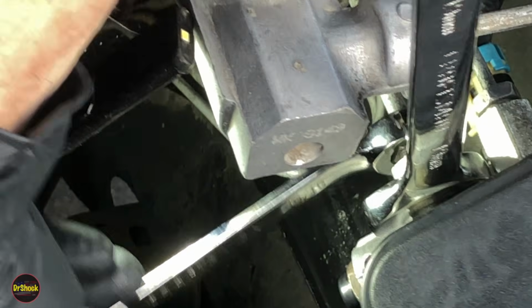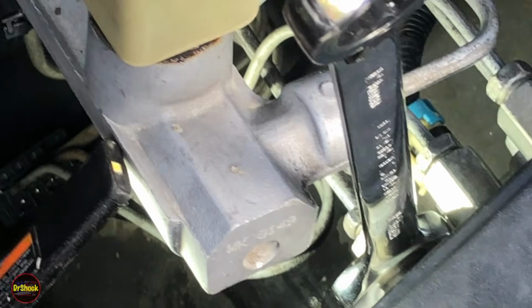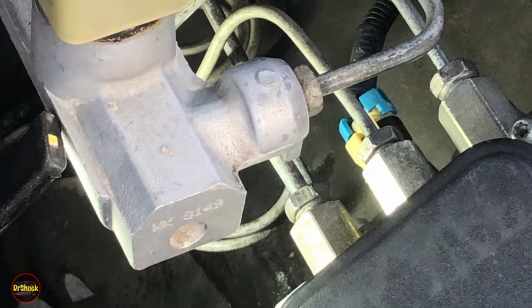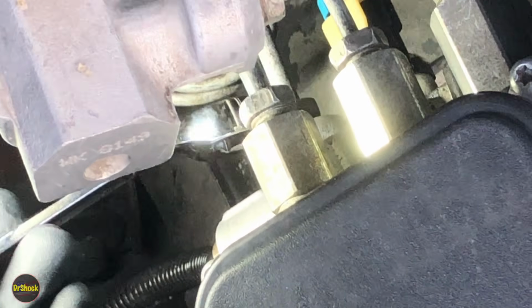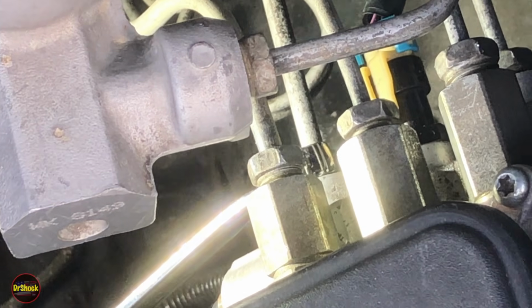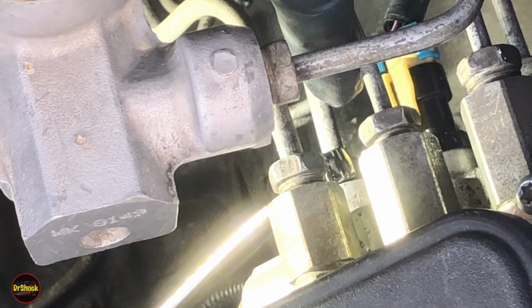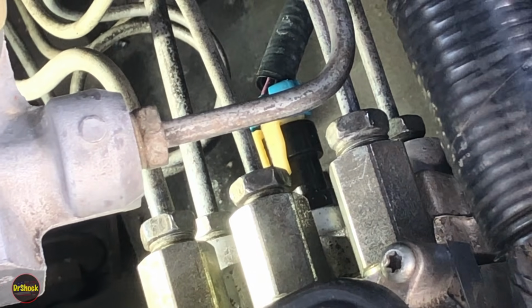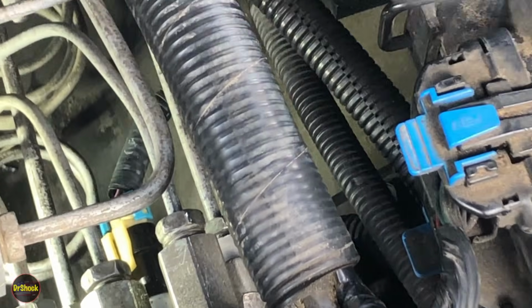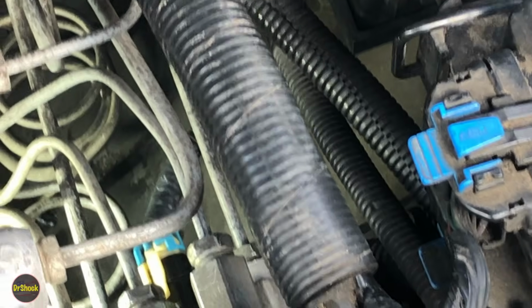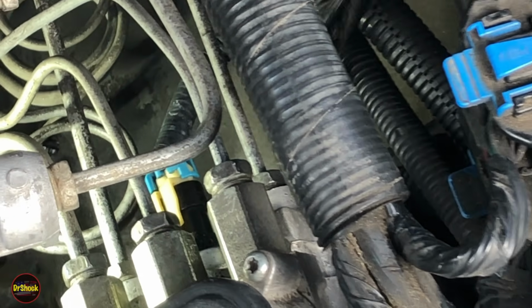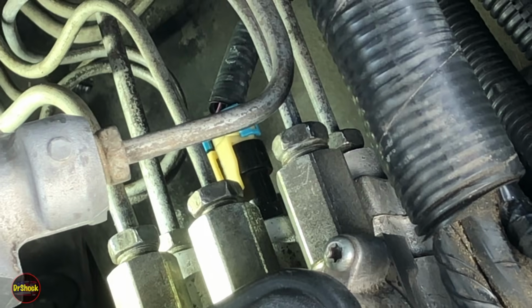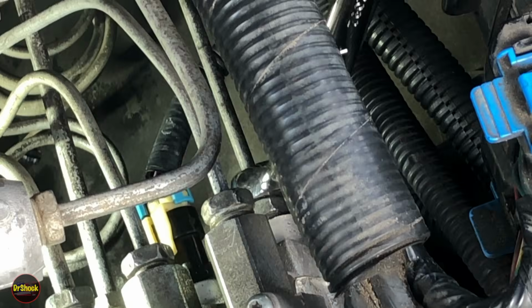Now the ones on the bottom, we don't need the 19 because we don't have these tubes up here. We'll be able to come in, and again, it's probably easiest for the camera to look straight down. We'll come in here with the line wrench and grab this one right down there. The ones that are hard are the ones closest to the fender. You can come in between the VCM, if you've got a gasoline engine, and the fuse relay center in order to get the one on the very bottom. Sometimes it helps to give this a turn. They usually have a bend to them. We'll get this one on.